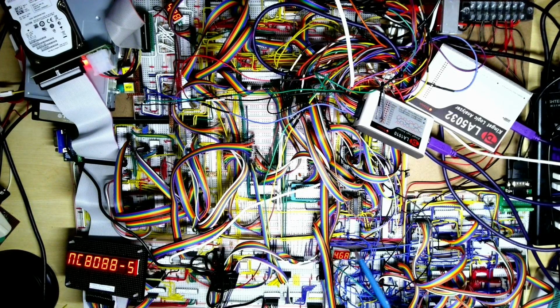You can see down here we've got little mini voltmeters. There are a number of these mini voltmeters around the board, and this is because sometimes you'll find that the voltage can drop quite a lot. In fact, on one of the early versions of the 6809 Nanocomp, I found that the voltage in one corner of the board was about 3.5 volts, and that will definitely cause you problems.